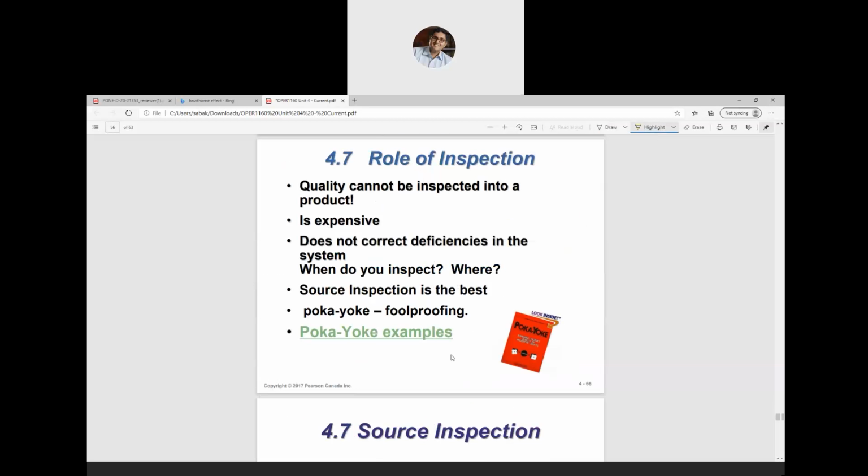Now, we speak a little bit on inspection. We spoke about quality. Whenever you have a quality team involved in the process, they will be checking whether things are in good shape or not. If you are trying to incorporate quality systems or quality procedures in your manufacturing process, you need to make sure that there's an inspection process to check whether the product is good or bad, and it has to be inexpensive. If the process is very expensive, it doesn't make sense. So what normally is done is what is called a poka-yoke, or foolproof.